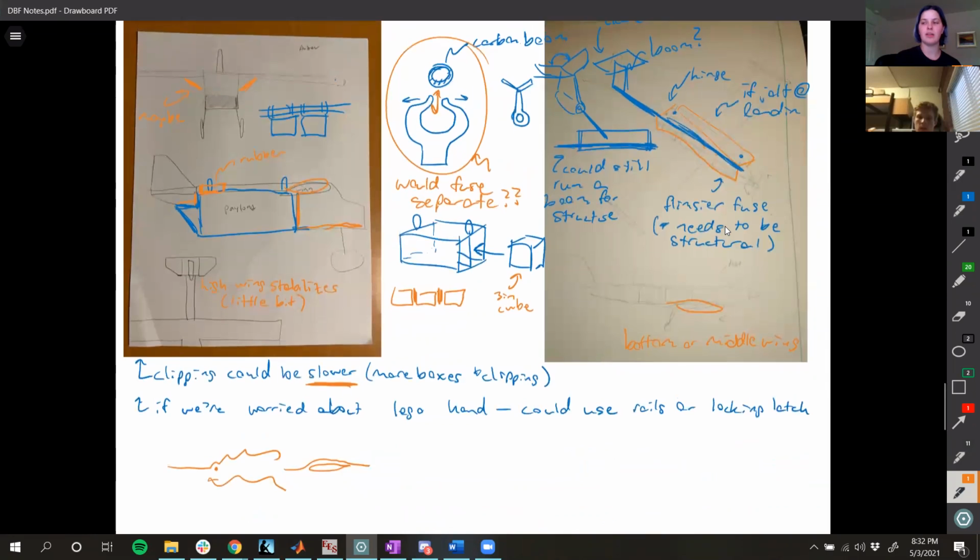So theoretically, you can make the spar less thick, considering the contributions of a structural skin. But the calculation would be a little bit harder because the airfoil is defined by points, and you can't do math on a set of points.